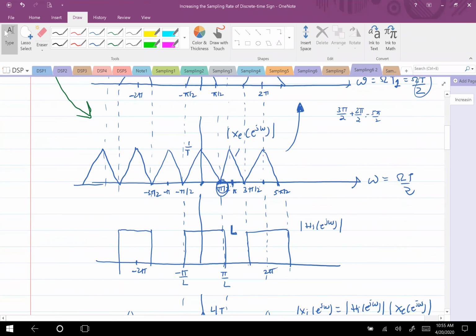The next step you could see there is you are going to interpolate them with a sinc function. That sinc function is having a periodicity again, so minus pi by L to plus pi by L. If you take the cutoff frequency, in case of capital omega scale, you take it at omega s by 2.